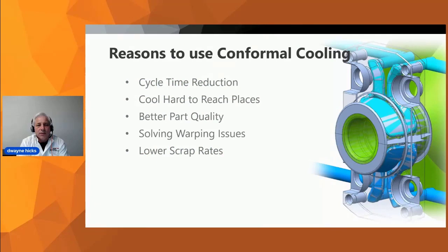I have customers tell me that if I can reduce cycle time by even 1 second, they are interested. 1 second may not seem like a big deal, but if we consider the tool is projected to produce 1 million parts a year, well, how much is 1 million seconds? With proper conformal design techniques, we can considerably shave several seconds off of each runtime. It doesn't take much to save a month of processing time.